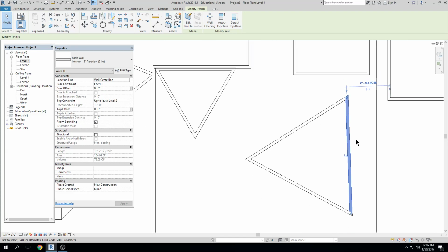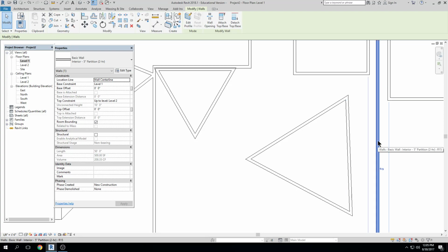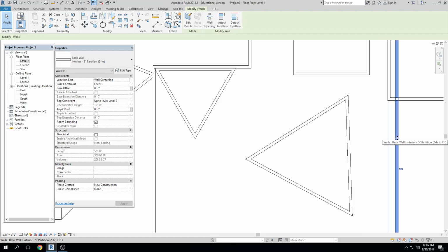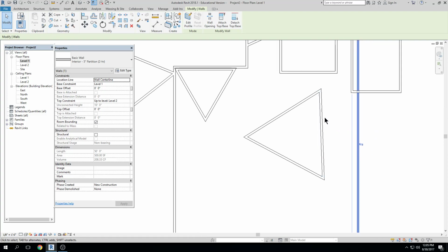But this is a very simple drawing. If there was a floor on here and there was furniture below and there were bearing walls below and there was a foundation and footings and all this stuff, right? And I clicked here, I could accidentally grab all of those items. And by doing that, it would really kind of mess everything up, right? So I had intended just to maybe move this wall, but everything below it moved with it when I dragged it, right? So dragging is maybe good for moving furniture. I'd even just be very careful with it in general, okay?